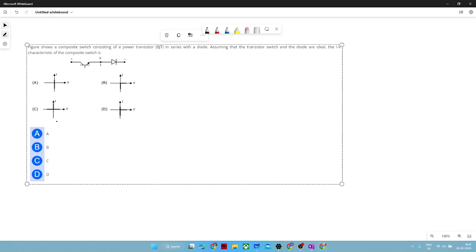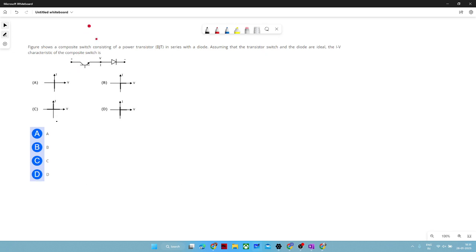So again, a very simple problem, right? So we will again apply both types of polarities of voltage. So let us assume when positive voltage was applied across both the terminals. So this transistor will block positive voltage. Okay. However, this diode will block negative voltage, right? So it is satisfying the criteria of bipolar blocking capability.